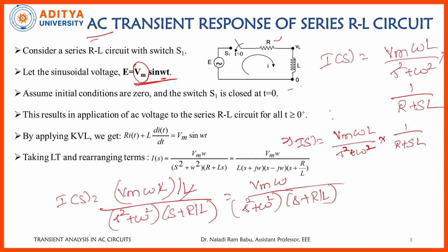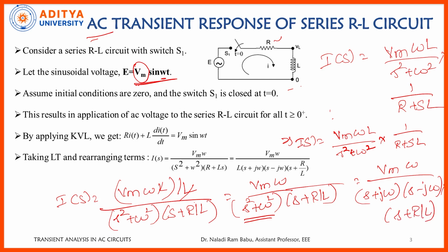Here it is a second order expression, so I am trying to reduce it into first order. I am writing it as Vm into omega by s plus j omega into s minus j omega into s plus R by L. If I multiply these two parts, it will be s square plus omega square.